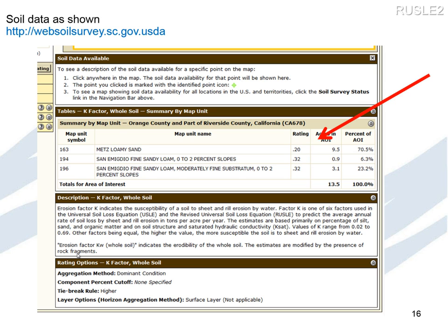To put this into practice, you would look at the area of the site that's represented by these certain K factors and do a weighted average. If we have 9.5 acres of this 13.5 at 0.2, we'd areally weight that. So 9.5 out of the 13.5 is 0.2, and the rest of it is 0.32. We'd have a weighted average K factor, and that's something you can manually enter into the RUSLE2 model under that soil tab. So that's the first method.